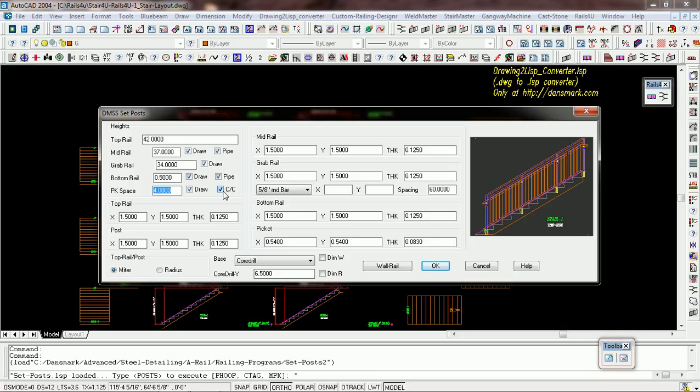Unchecked means that it will use a 4-inch reject. So there, it could be pickets of different spacings that will reject 4 inches, go all the way up to like 3 15/16, but it will reject a 4-inch sphere.